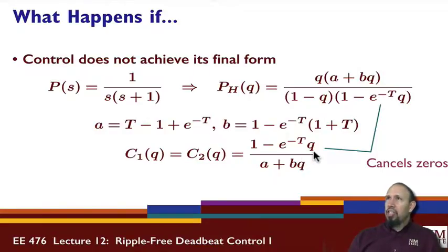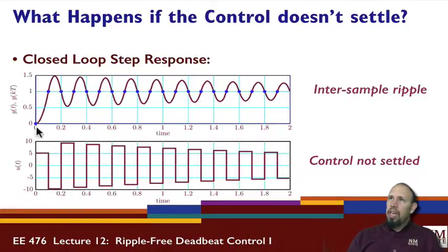Stable cancellations. But if you go through and simulate the system with this, this is the response we get. The blue dots are the response of the system in continuous time. Those are the discrete time values, the values we get at the sampling instance. So in discrete time, the system looks like it's stable, and it looks like it's settled at this point, right? But if you actually look at the continuous time signal, you can see that basically you've set yourself up to do aliasing.